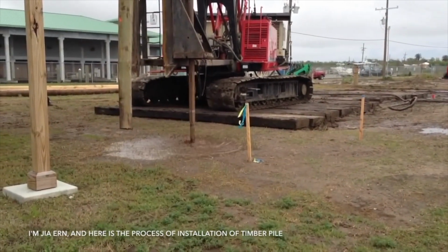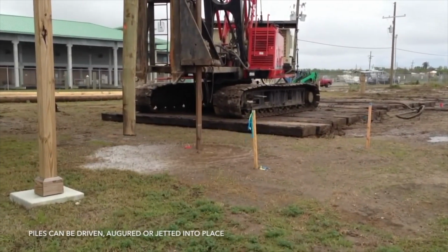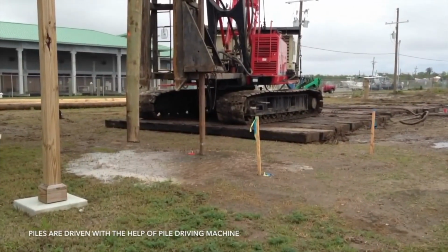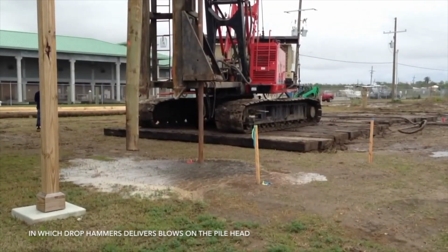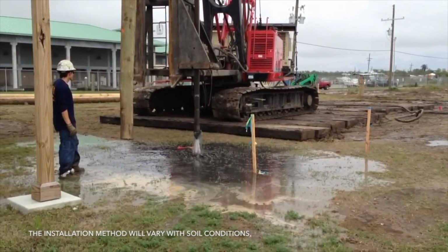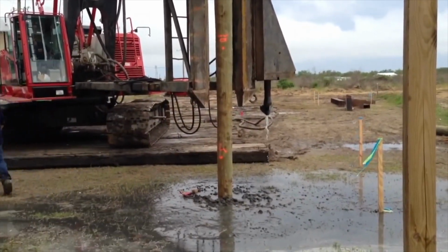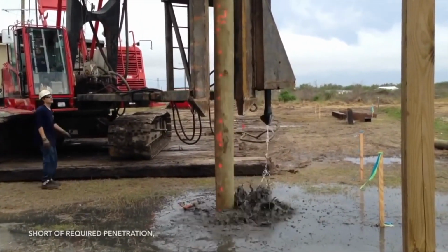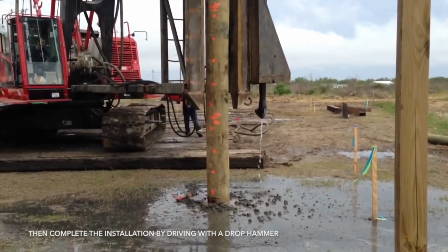I'm Ja'er, and here is the process of installation of timber piles. Piles can be driven, augered, or jetted into place. Piles are driven with the help of a pile driving machine, in which drop hammers deliver blows on the pile head. The installation method will vary with soil conditions, bearing requirements, equipment available, and local practice. One common method is to initially jet the pile to a few feet short of required penetration, then complete the installation by driving with a drop hammer.